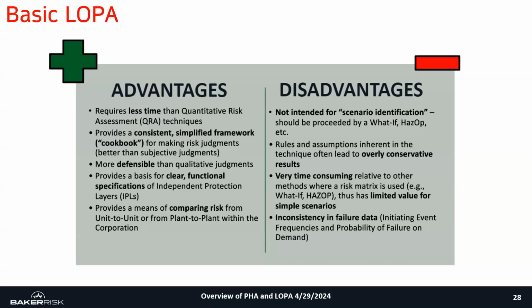LOPA can be very time consuming. It definitely takes more time because you're digging into more detail in your initiating events, your safeguards, and ascribing probability of failure on demand, which we'll talk about in a minute. So while LOPA is very time consuming, it's best used for your more complex scenarios.